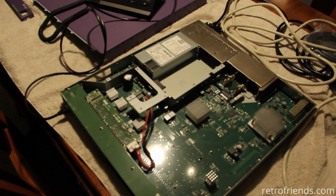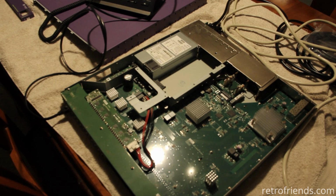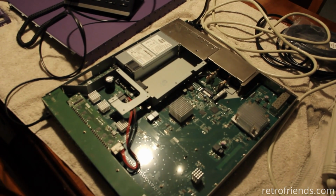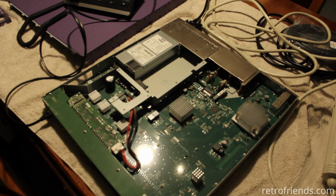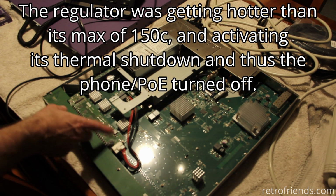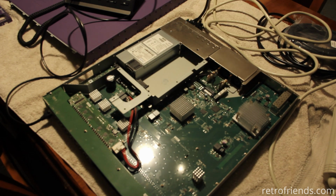Thought the job was done. But I thought wrong. The IP phone stopped working and then it came back on, and then I decided to feel the chip that I installed with my finger, and it's red hot. So I'm going to go and test the passives. There's not that many of them.